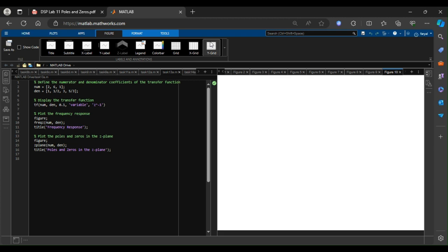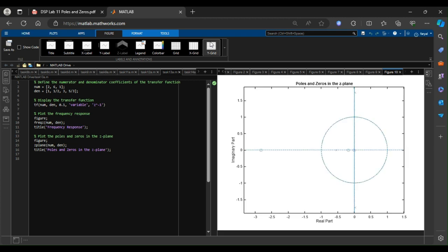Moving towards the frequency responses, the location of poles affects the frequency response of a system. Poles closer to the unit circle influence the system response at higher frequencies, while poles closer to the origin impact low frequency responses. I have already talked about resonance and damping: poles closer to the unit circle contribute to the resonance phenomenon, where a system amplifies certain frequencies. On the other hand, poles farther from the unit circle contribute to damping, which reduces the amplitude of oscillations.